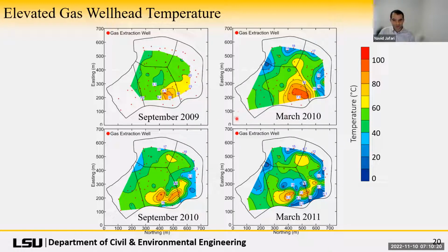As we move forward to March 2010, we still see that the gas well temperatures are quite high, but we also see a lot of blue points here. And I think that is a problem with using gas wells as the only signal for an ETLF. If you do get air intrusion, maybe there's a seal broken with the gas well that lets air directly into the well, you're going to see these cool spots that are more than likely not reflecting the actual waste temperatures.